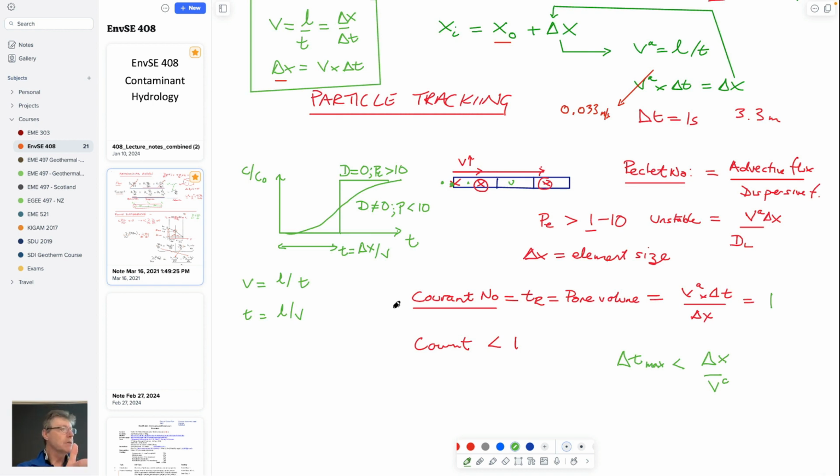If you don't know what you're doing with the code and you do something like use a time step which is too big that doesn't keep the solution stable, or use a Peclet number that is too large. The one way that you can keep the Peclet numbers small is that you could use, again, a grid which is much finer.